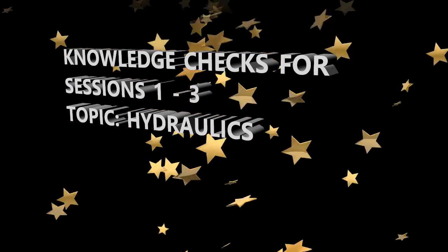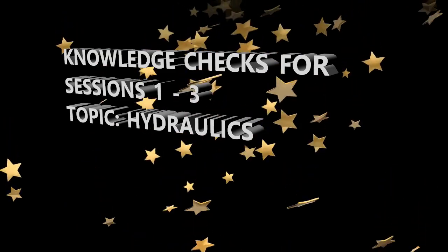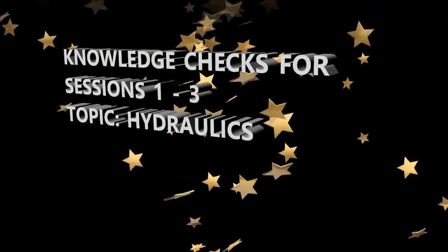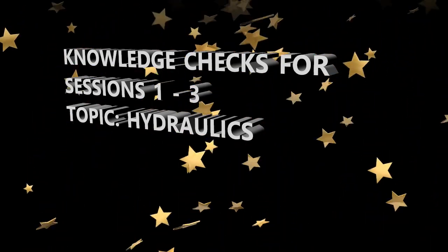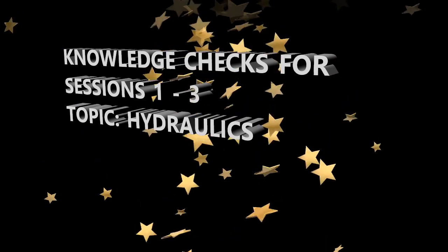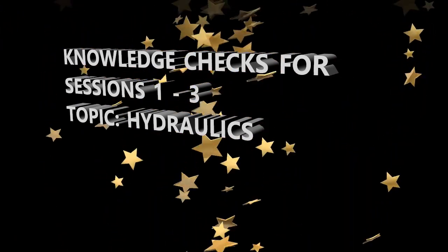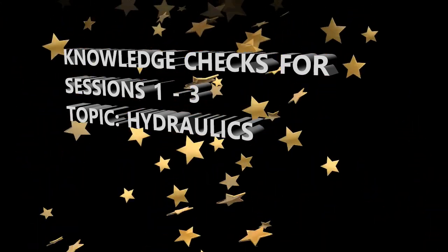Is that true or false? That's a true statement. Okay, number 5, the yellow hydraulic system components are located in which belly fairing? The right belly fairing or the left belly fairing? Okay, it's the right belly fairing.